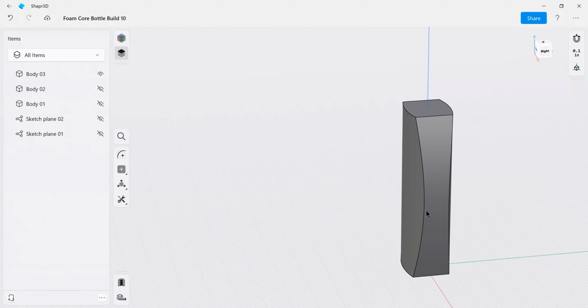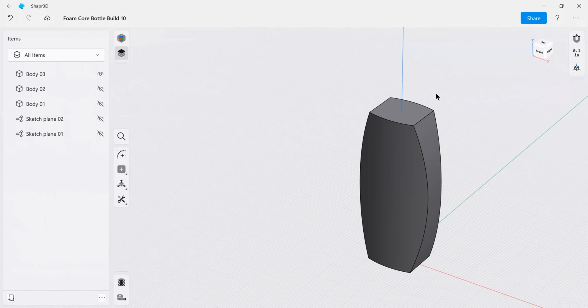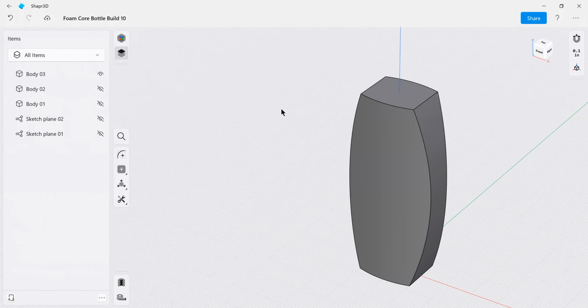What I'm going to do next is radius these corners. I'm just going to radius these four corners because we can accomplish that in the cardboard and the foam core. I'm not going to do any compound curves. Normally this side surface here would have an arc to it, so we could have our nice parting line and our draft angle to get out of the mold. But since I just want a 2D drawing to make a foam core model of this design, I'm going to keep that very clean at this point. I will show some other tutorials on how to incorporate draft angles and things like that with this type of design configuration, but we'll do that at a later time.